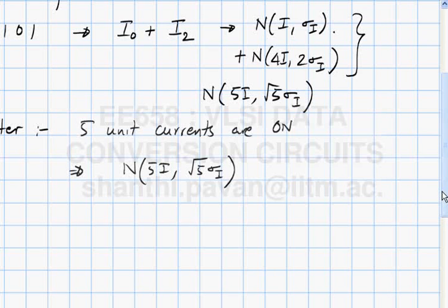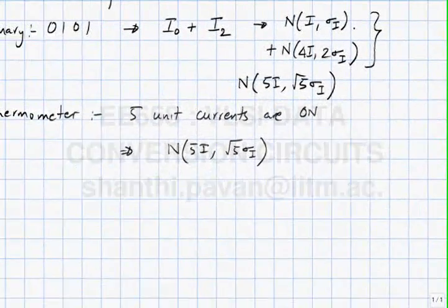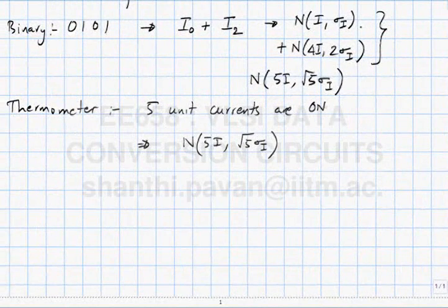So if you're only interested in INL, which is not often the case, then it doesn't really make a difference whether you do binary or thermometer. But in most cases, you're very insistent that the DAC should be monotonic, in which case the matching requirements on the unit elements become extremely tight for a binary design.